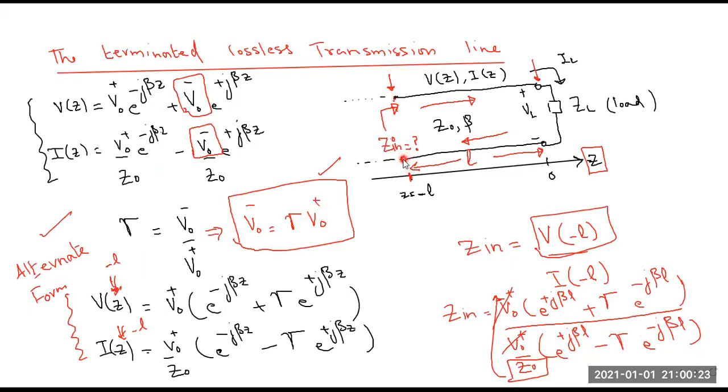The reason I'm calling it input impedance is because of the general structure of the circuit, that you will have a load, and then you will have some transmission line with some length, and then maybe we will be interested in finding out how much is the impedance at this point. So this point is input, but what I'm saying is, even if you find Z in at this position, then it still means that L is 0.